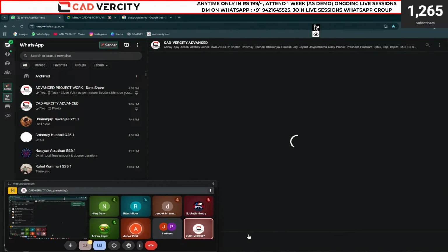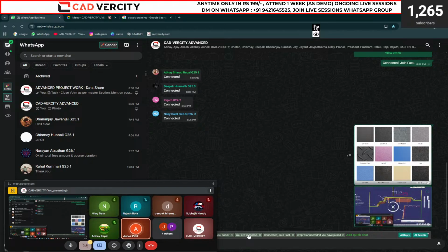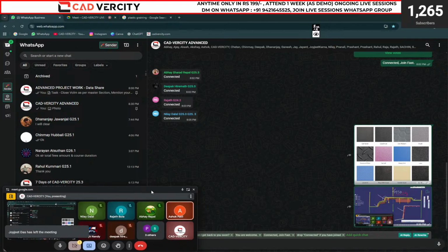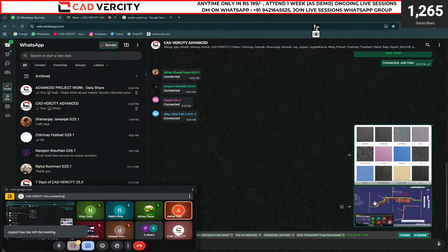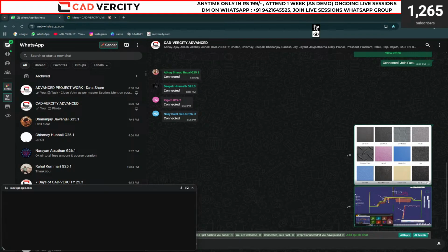Sir, I saw in the animation, while opening of core and cavity, that one of the core or cavity is fixed, or one of the opening A style will mostly be fixed. A style. Okay. Depending. See, the ejector pin will be from the B side every time. Okay. Let me check, just a minute.